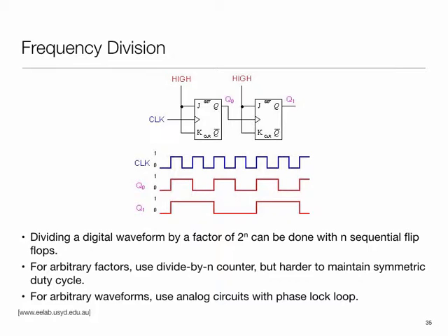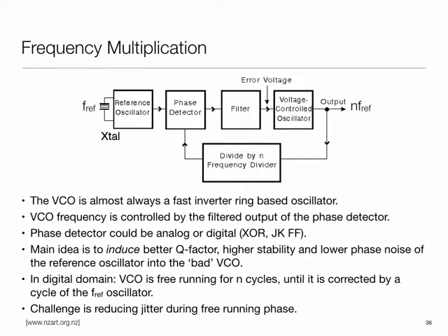If I were to divide by an arbitrary n, the problem that begins to happen is that I want to have evenly spaced clock edges. Then things get tricky, because let's say I'm dividing by 3, then strictly speaking, my edges will have to lie in between the edges of the original clock, and that is tricky. How could we pull those kinds of divisions off? So this leads to the concept of PLLs, or phase lock loops. And the way it works is the following.